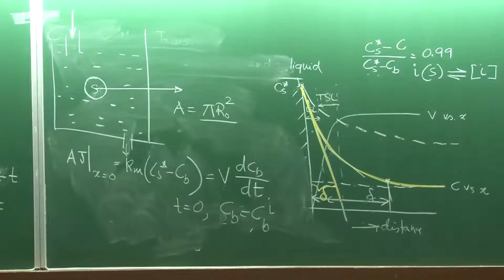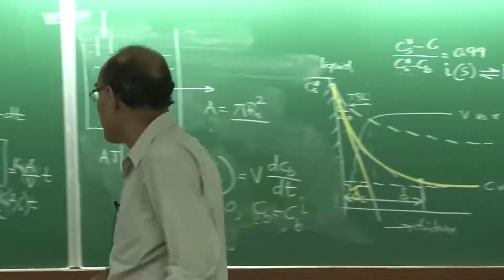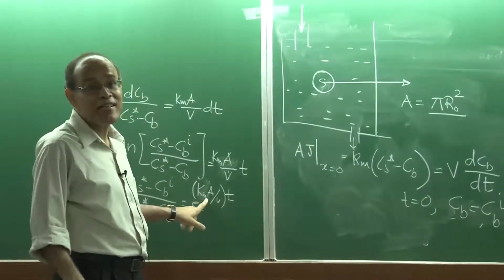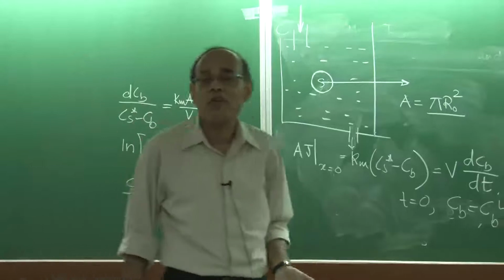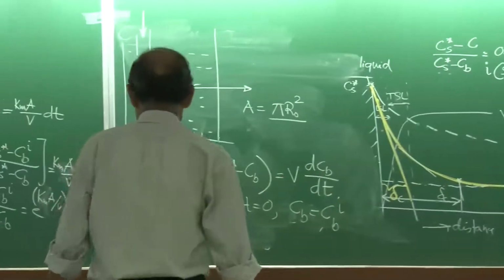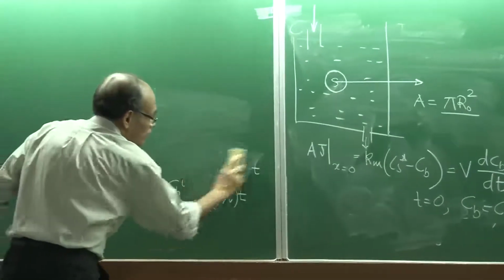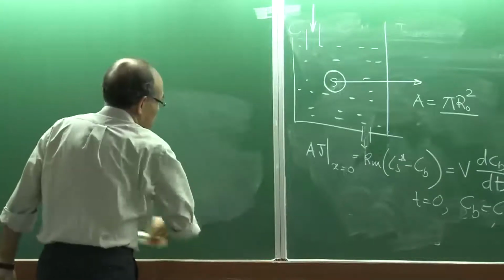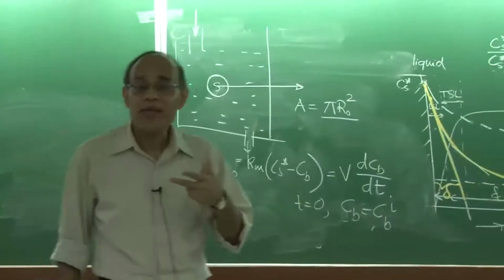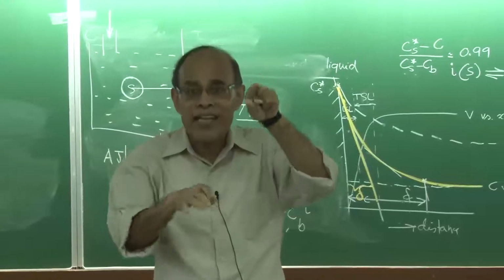So it turns out that we are now concerned with the calculation of the mass transfer coefficient, and the problem boils down to exactly what I have discussed in the context of heat transfer. Mass transfer coefficients are calculated from mass transfer correlations, and we have free convective and forced convective mass transfer correlations, as I indicated earlier in my lecture on heat transfer. In free convection in heat transfer, it is the temperature gradient that causes the density differential and drives the flow.